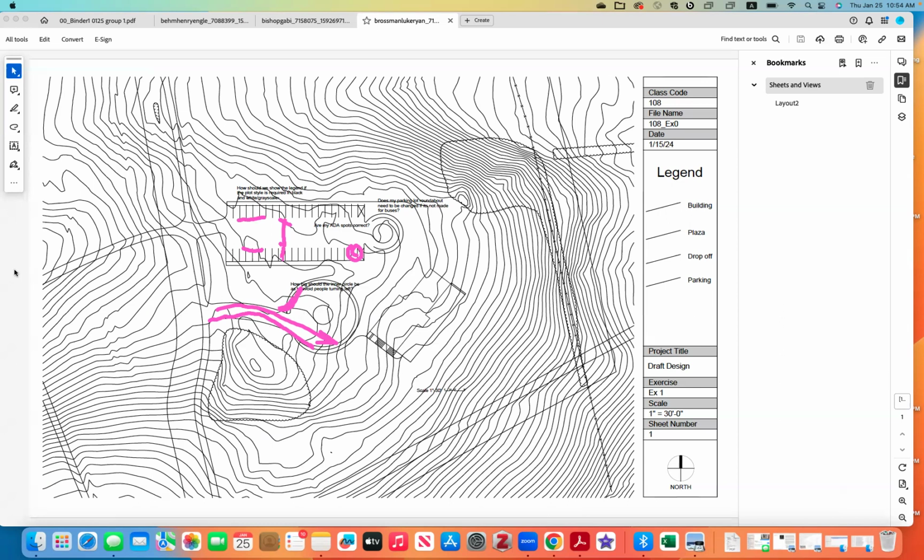Okay, same issue. We should be 50 feet away from the vegetation, so this whole thing needs to be moved north. Your building is on a flatter area than desired. Okay, so you could push this down to once the building crosses like 5 to 6 contours.